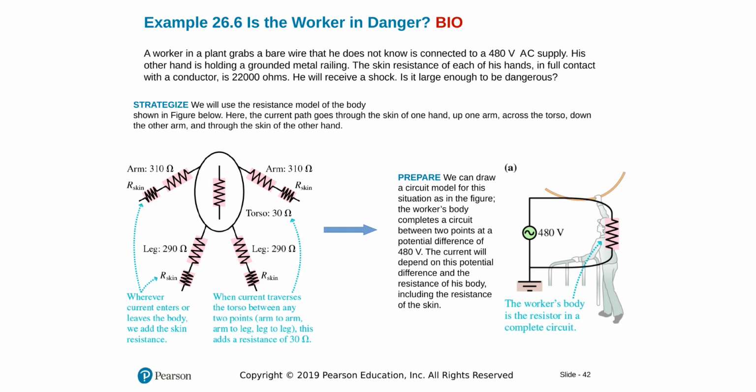So this question here is about a worker who by mistake touches a wire that has an electric leakage. A very big mistake he has made is to touch a conductor that is connected to ground. So what will happen here is current will be able to complete its path throughout his body. We'll have a complete circuit. He touches a high potential here, and a low potential there, which is 0. Overall ground potential is 0 volts. Current will flow. And the high potential he touches is 480 volts.